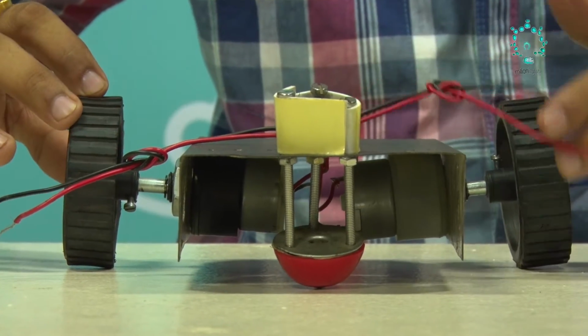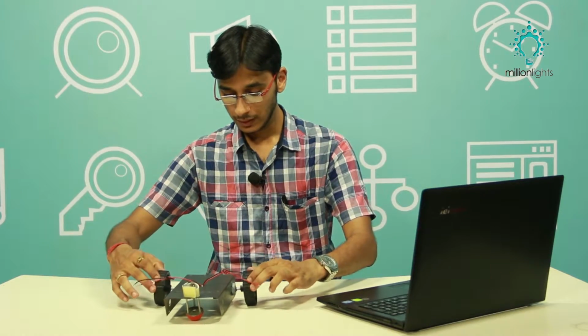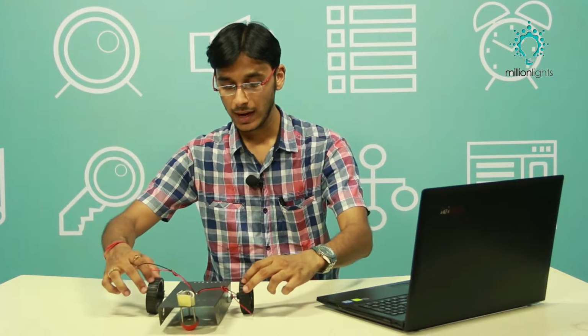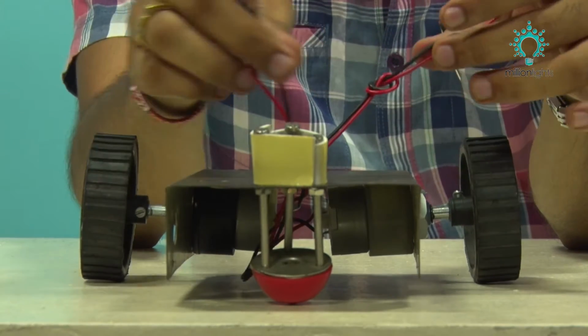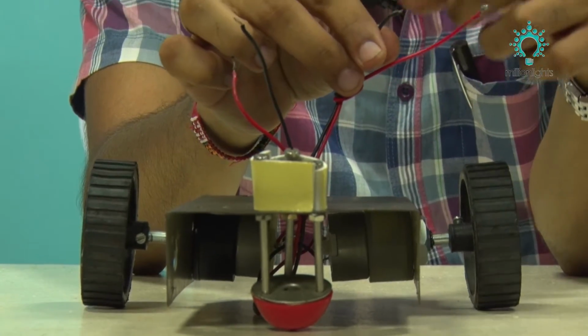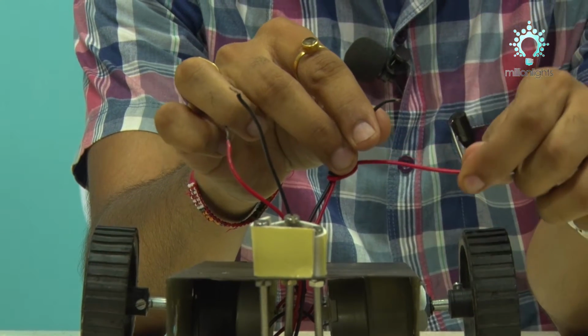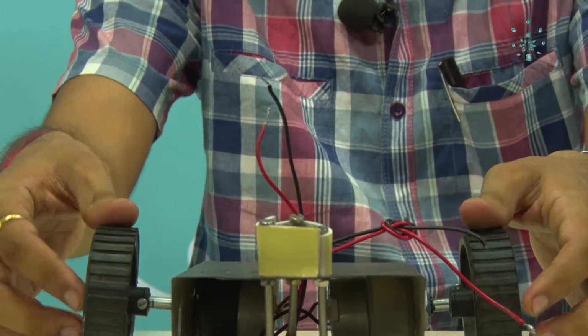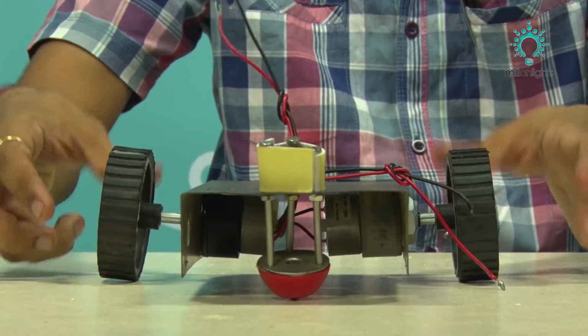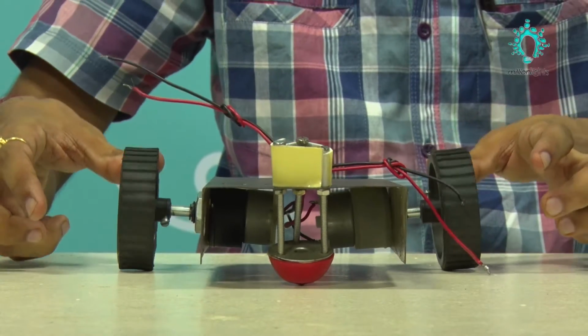As you can see, I am manually moving the motors, so this will move forward. If you are giving supply to it and both are in the same direction, then it will move forward. Now if you want to bring it in the reverse direction, that is, backward, then what do we have to do? We have to change the polarity. To this black pin I have to give plus 5 volts, and here I have to give ground. The same thing is repeated, and this will start coming back. So depending upon your requirement, you can make it move forward or backward.